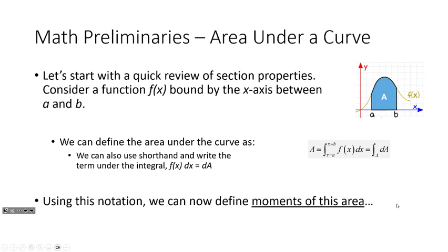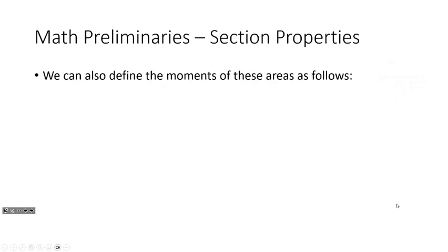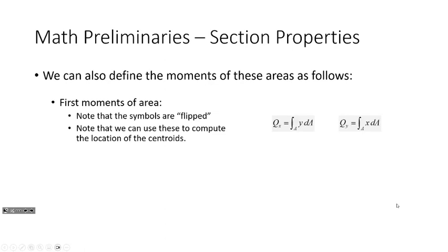Now in calculus land, how do we define the moment of a function? Well, if the area is the integral of dA, then the moment of a function is the integral of x dA or y dA, okay? So first moments of area would be the integral of x dA or y dA. And we can use these to compute centroids.